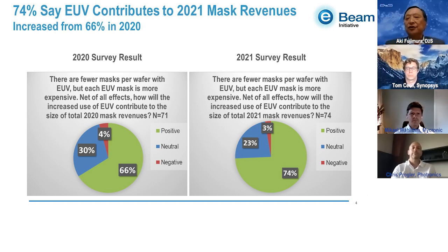So you're saying that traditionally mask write times were the dominating factor, but these days it's more than that. EUV masks are mostly written with multi-beam, and despite that, you think the mask costs overall are going to go up, even though the write time is the same, and complex shapes are still going to cause EUV masks to be more expensive. Yes, I believe so.